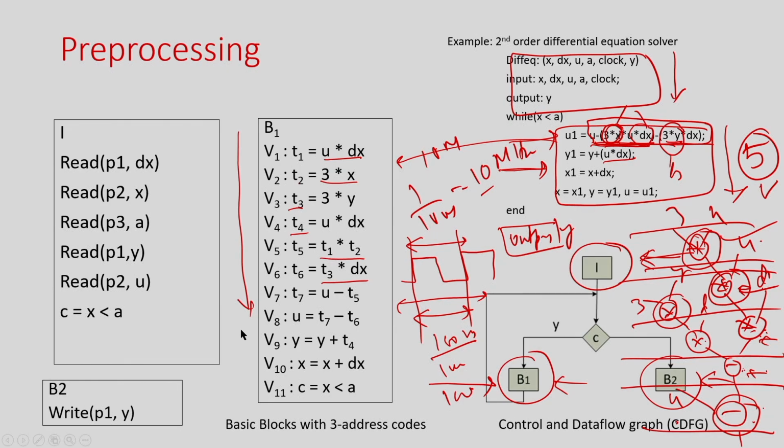Okay. And why do we need that? Because these are the unique operations or the unit operations that are to be scheduled. We already understand that I cannot execute the complete expression in a single clock, that will make my circuit very slow. So, I need to identify the unit operations, and this is called 3 address operations. So, this is what you have to do first, that you break this bigger expression into smaller unit operations, which is called 3 address operation, and then as I mentioned, to identify which operation to be executed where, you need to identify the data flow, right. So, data dependency, how we can do that?